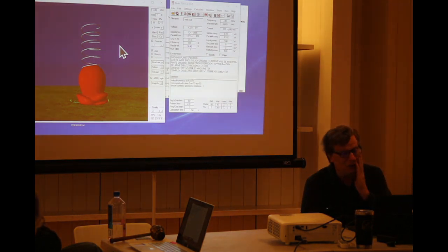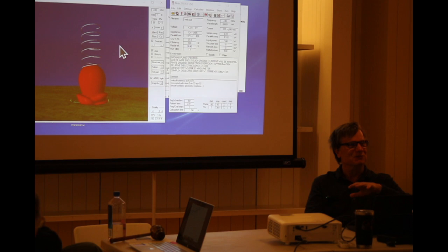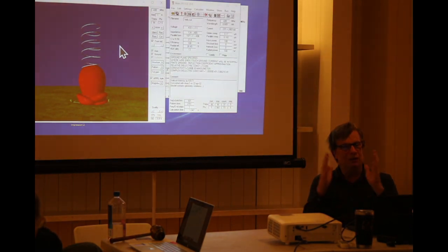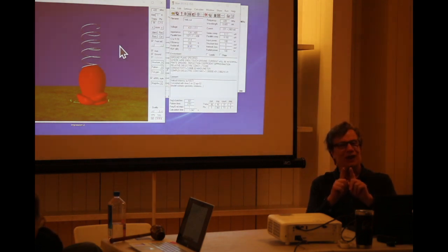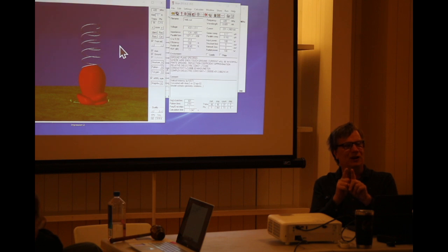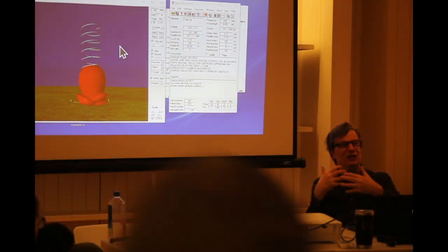I worked on the TPS-77 radar at Eielson. It had 172 elements, but it was a close-spaced array because it had to be a clean pattern. You can't have side lobes when you're tracking military aircraft. But what's really interesting, the spacing was so close that the interaction between them radically changed impedance. So every one of those elements had a 90-degree hybrid and a dummy load that burned up half the power. That's the price you pay with a close-spaced array. So they're actually dissipating half the power there with the reject loads on each of those dipoles.